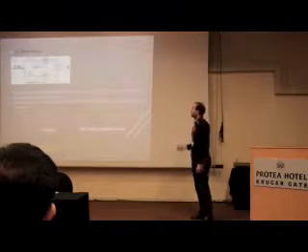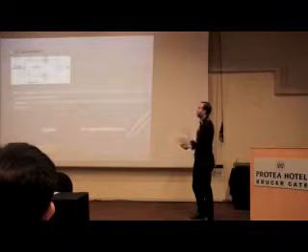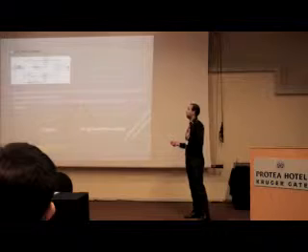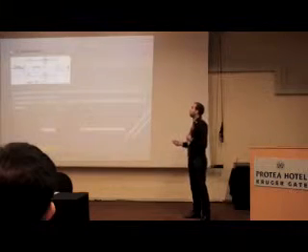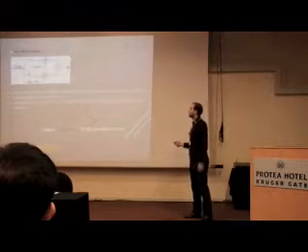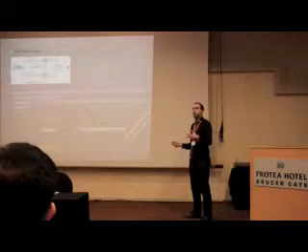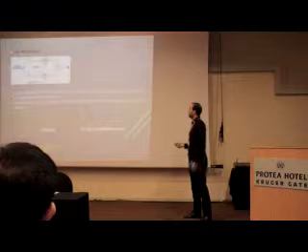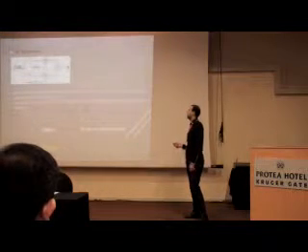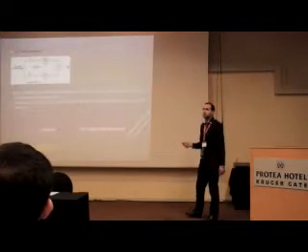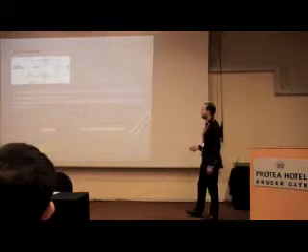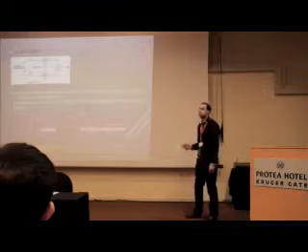Okay, so this is just to explain to you how the IQ modulator is working. For me, I have two signals, one in-phase signal and one quadrature signal. I can just send them into the FMCOMMS1 component. The first signal and the second one are 90 degrees out of phase, so there is the original one and the 90-degree phase-shifted version.